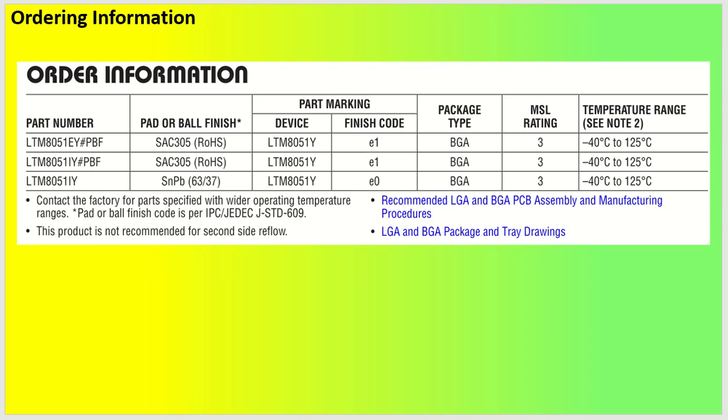Coming back to ordering information, it has three parts. One is LTM8051 EY, then another one is IY, and another one is without lead finish. PBF is with lead finish, and without PBF is no lead finish. Our utilized part was the first part, which is LTM8051 EY PBF.